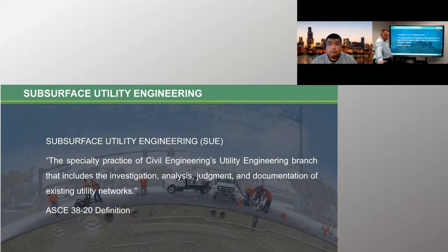It utilizes several processes and technologies, including records research, surveying, surface geophysics, and vacuum excavation. And in the new ASCE 38-20 standard that will be ratified this year, the definition is: the specialty practice of civil engineering's utility engineering branch that includes the investigation, analysis, judgment, and documentation of existing utility networks.